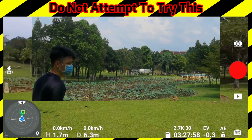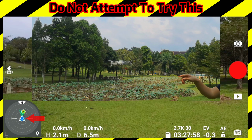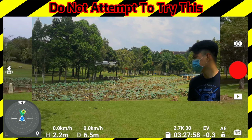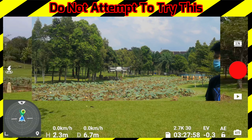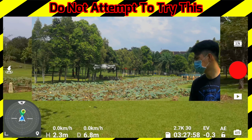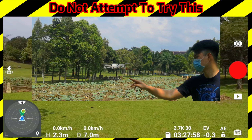Once we are familiar with how the tilting line reacts in normal wind conditions, when it comes to windy conditions and you notice the combination of tilting line and aircraft speed is not normal, you will already know the wind situation on top and can take necessary precautions.